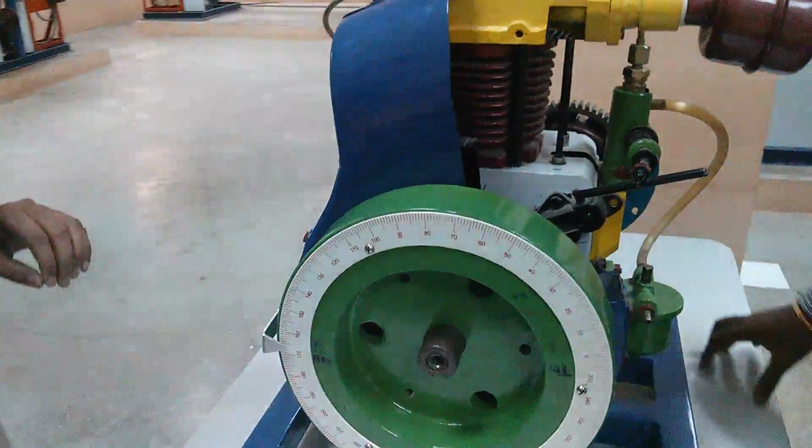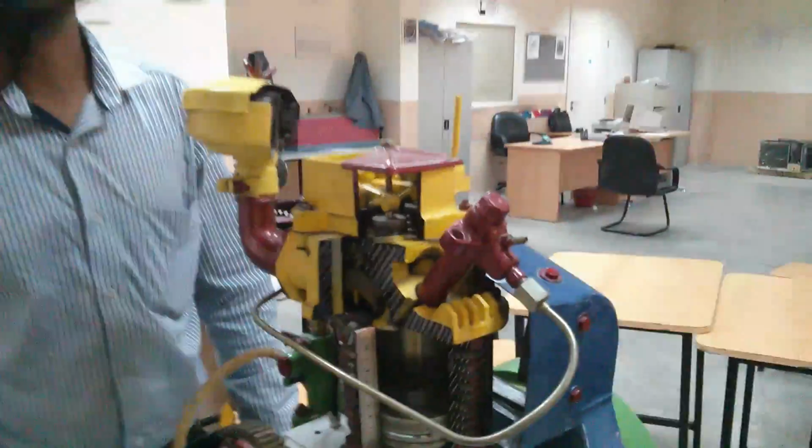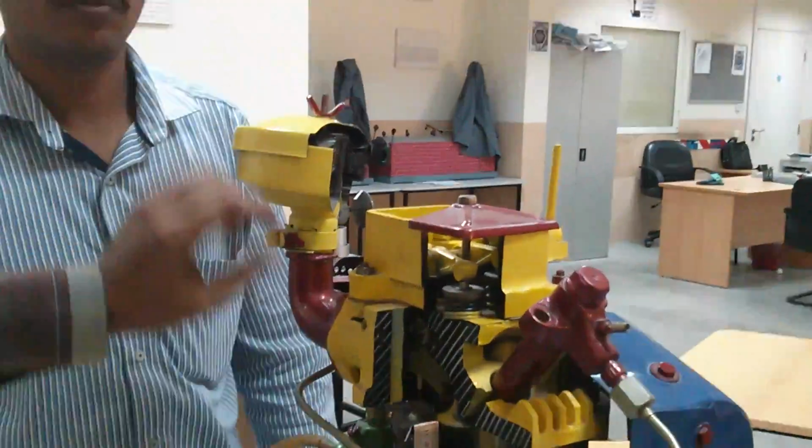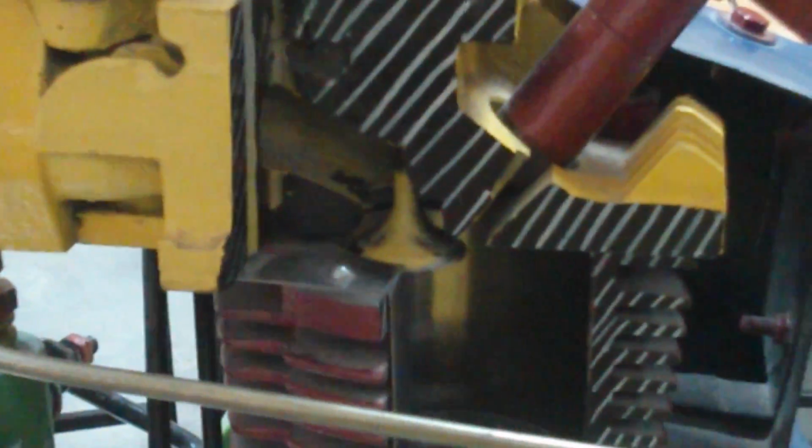Okay, the first is the inlet valve. So you need to identify your valves, which is the inlet valve and which is the exhaust valve. Coming over here, this is my air filter, right? This is my inlet manifold, and this is going to my inlet valve. So this is my inlet valve, and this is the silencer, or the muffler. The one which is connected here corresponds to that, so that is my exhaust valve. Once you identify the inlet valve, the other one is going to be my exhaust valve, right?